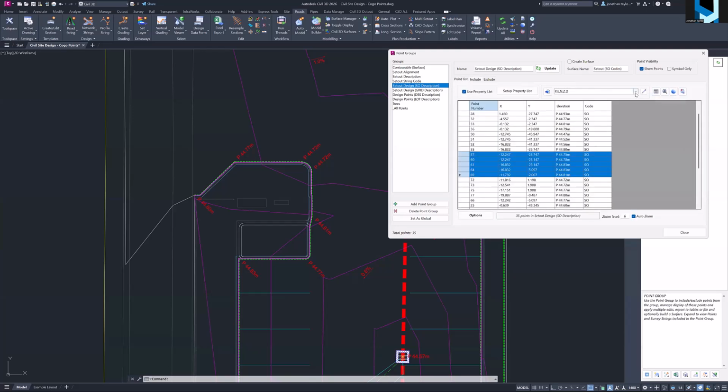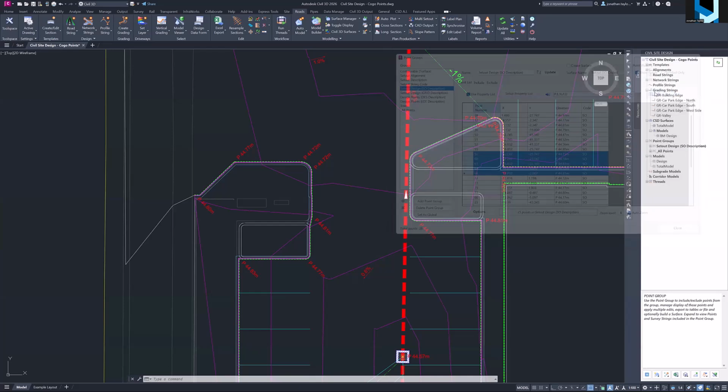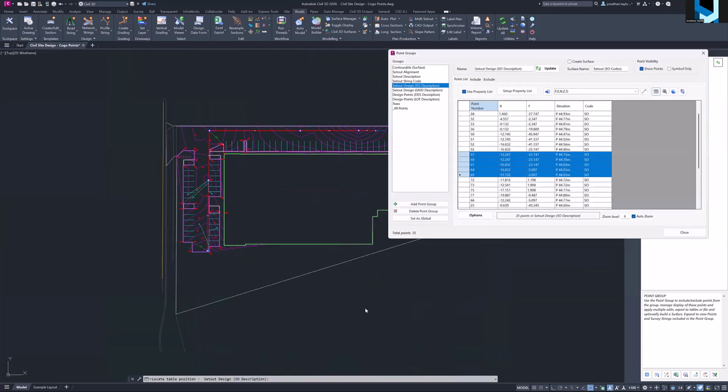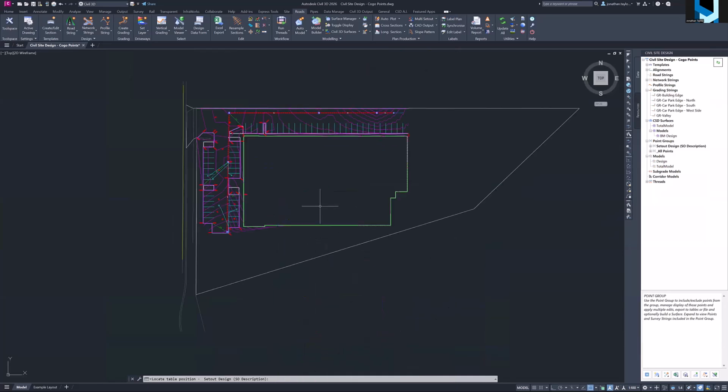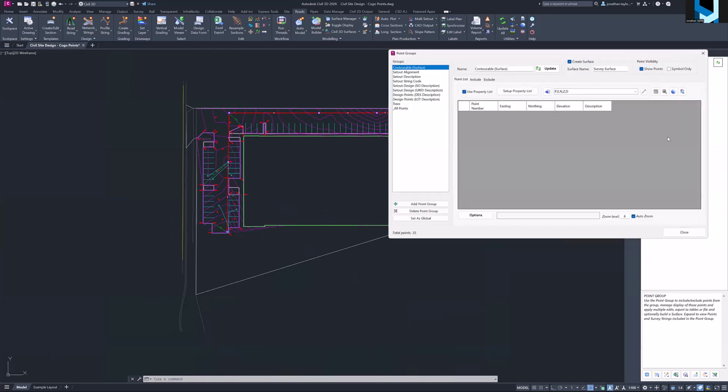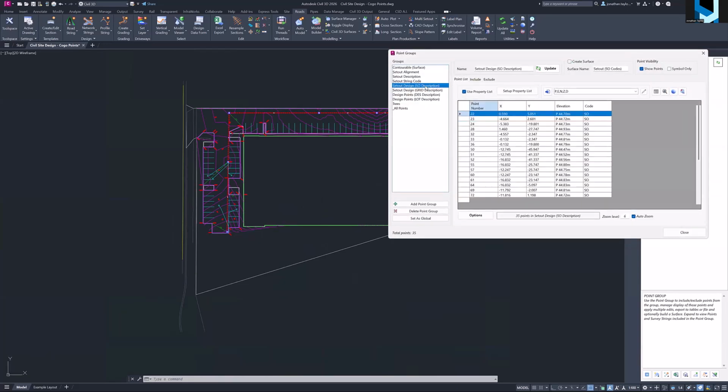Let's just go CAD table. There's a whole ton of options in here. We'll pop this over here. I was going to say, it comes down to what you want to do with the set out table if you wanted to do it in the drawing. That's the pit schedule. Hang on, just one second. Sorry, go on. That didn't work, so I'm just going to go back in and do it again. You could do exactly what Jonathan's doing there, where you pump out the CAD table, or you could pump out the CSV file and bring it into Excel, depending on what you're looking for.